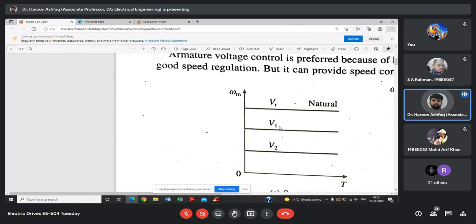इसका मतलब जो लोड कर्व होता है इस पे, जैसे हमारे पास T ओमेगा कर्व पे लोड कर्व आपने बना लिया कोई सा भी कैसा भी, then you change the motor characteristics such that the operating point of that motor load system changes, and the load torque characteristics are not altered anyway, only the motor characteristics are shifted. So if there are certain conditions in which certain methods or certain modification in characteristics yield to a desired point of operation. So you have the first method as armature voltage control method.